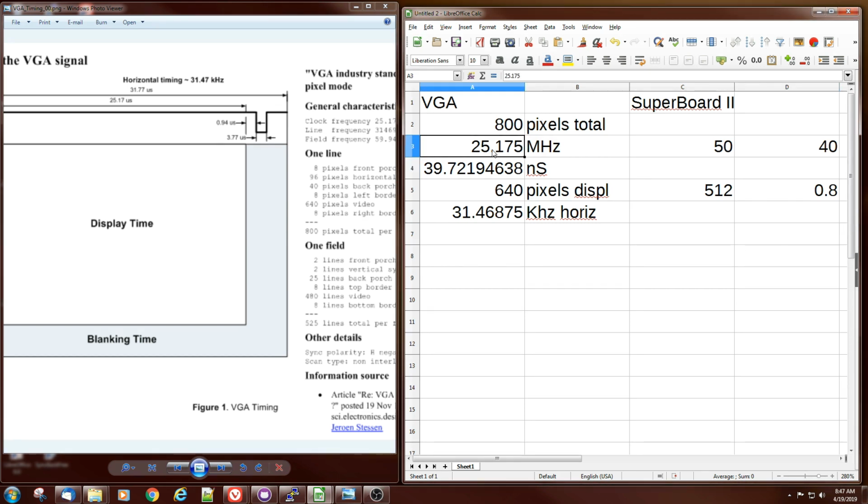But notice here that VGA uses a 25.175 megahertz clock, and the clock that's on the FPGA that's being used is a 50. So it's not exactly a power of 2, so this 40 number is actually a little bit off. So how do we get a clock that's about 40 megahertz out of a 50 megahertz clock? If we have a counter, the best we can do is divide by 2. Well, fortunately, the Altera parts have a phase lock loop inside of them that can generate almost any frequency you'd ever want to generate, but let's go see what it takes to set that up.